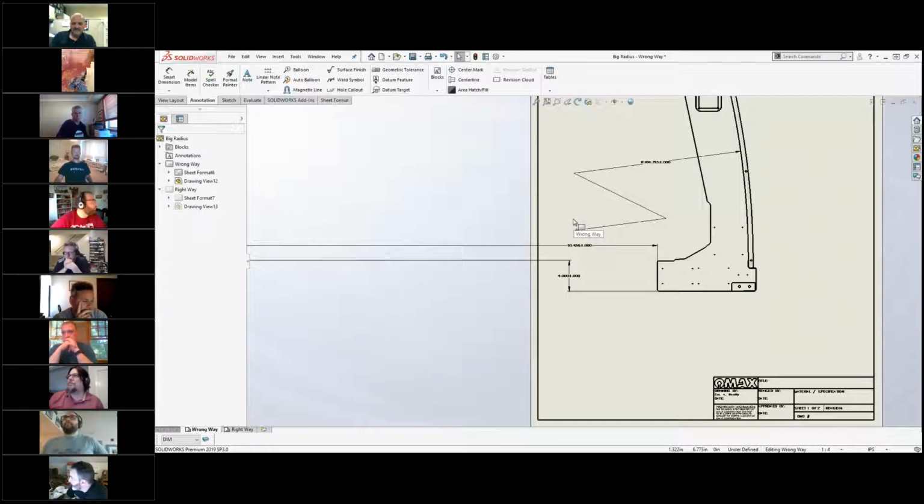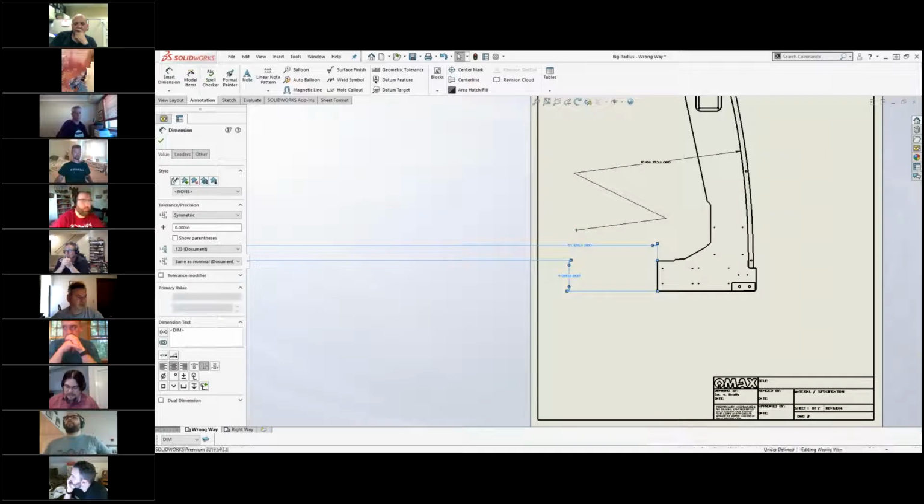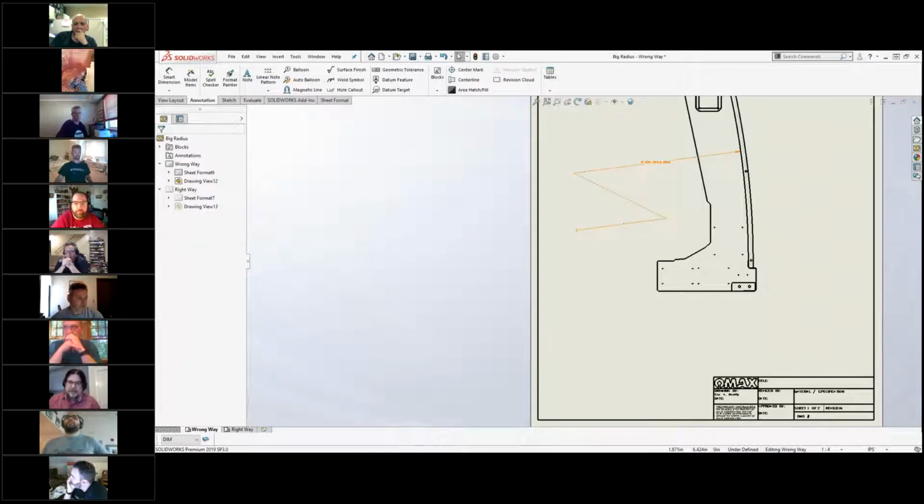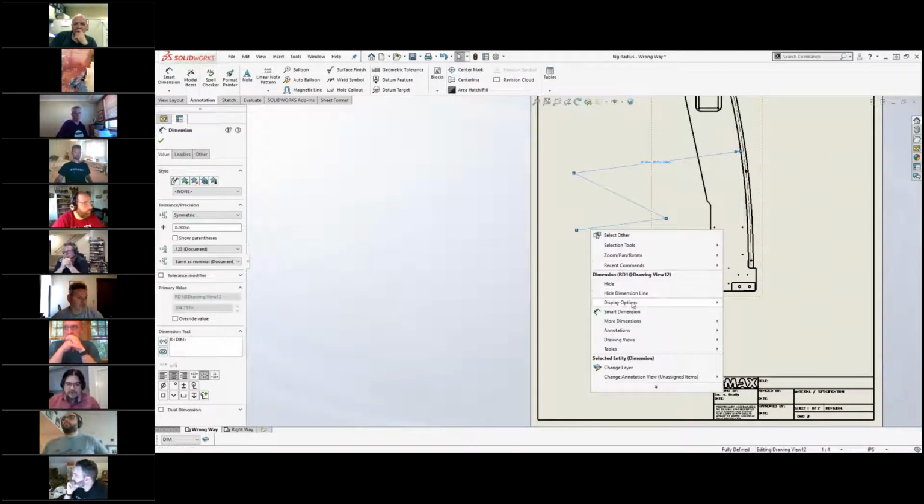I could keep struggling with this, but basically the thing to take away from this is if you're going to be creating foreshortened dimensions, especially for radius values, SolidWorks requires that you actually dimension to the feature itself here. So I'm going to get rid of these two, and I'm going to unforeshorten this one as well for a moment.